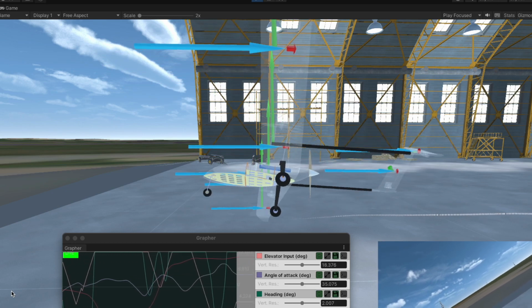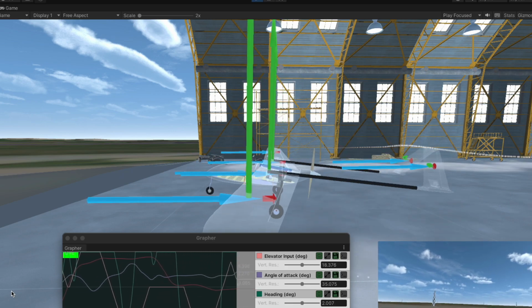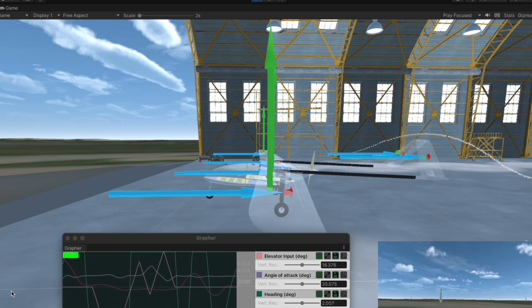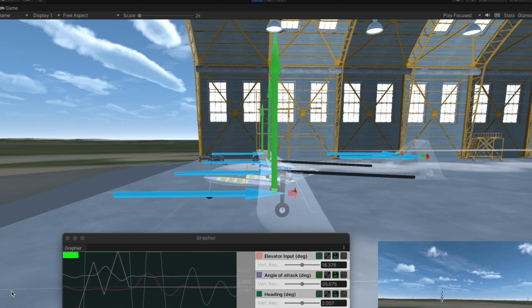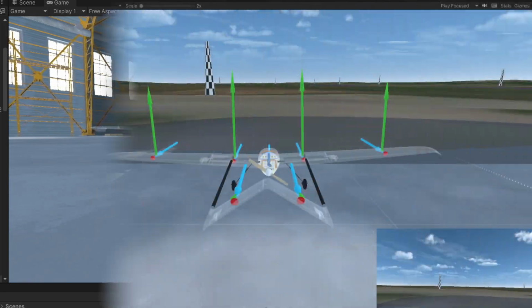We need to determine the sensible aft CG limit, which will ensure that the aircraft can be trimmed and maintains margin for maneuvering. For now, we will select 35% of the MAC, which places the CG at about 0.0815 meters aft of the datum point, which is the leading edge of the MAC.